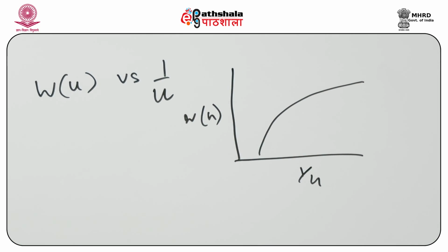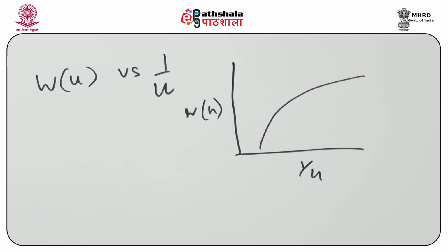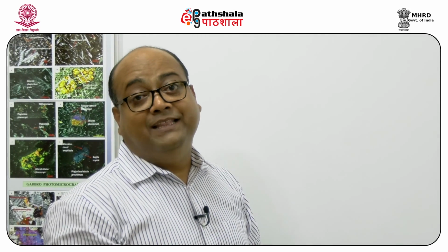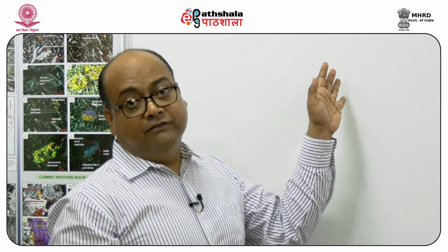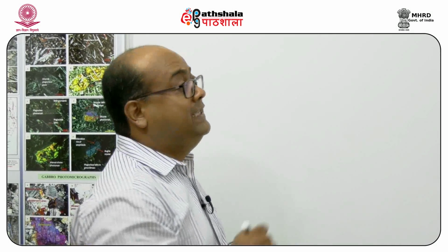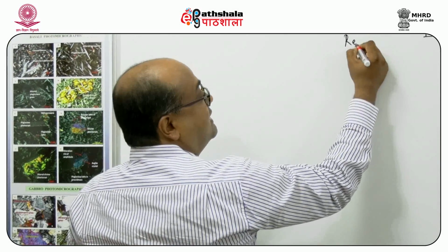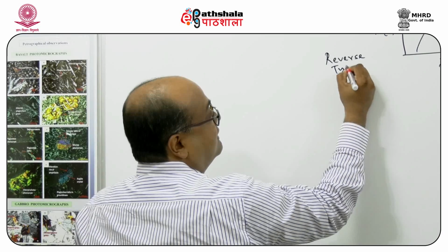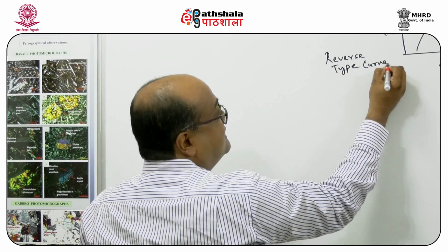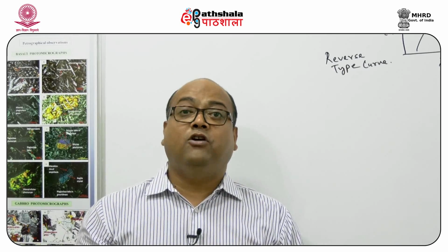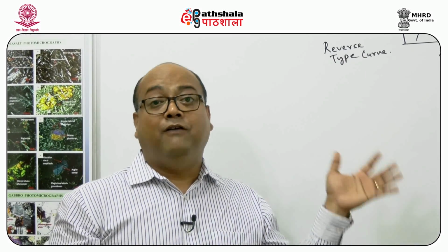The shape of the curve resembles the depression of a water table, and this is a standard curve found in any book of hydrogeology. It is known as the reverse type curve, and it is used for the graphical solution of the Theis equation or the Theis formula.